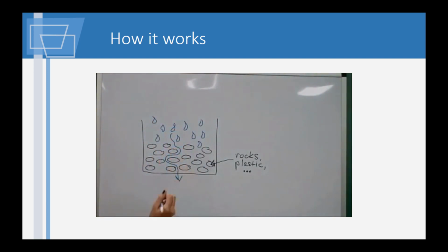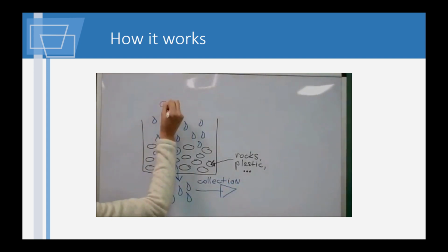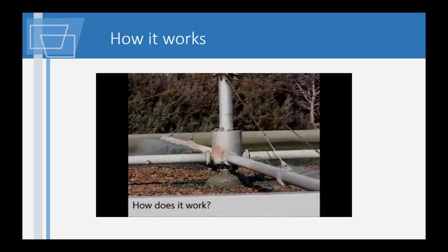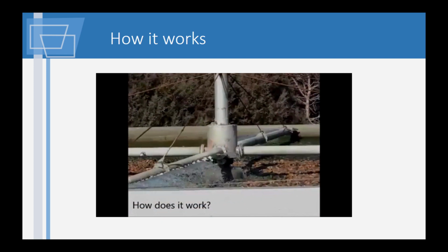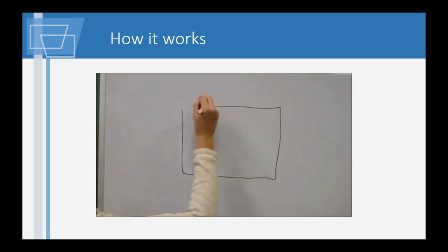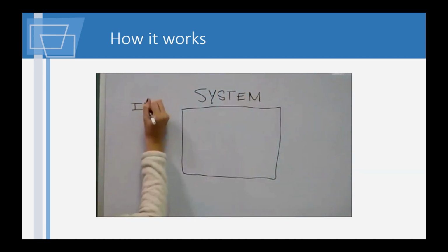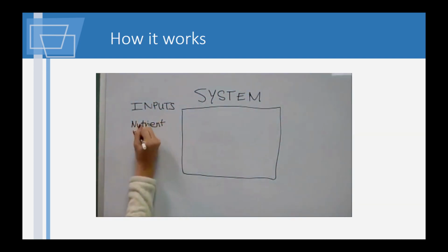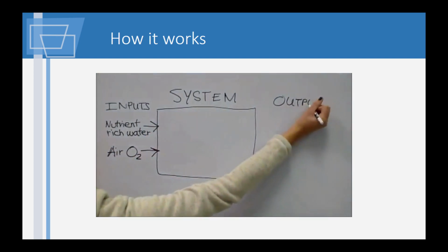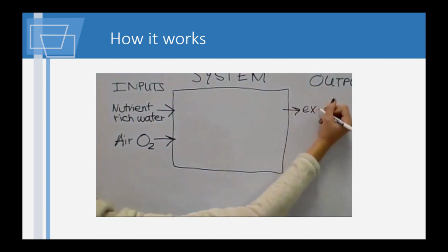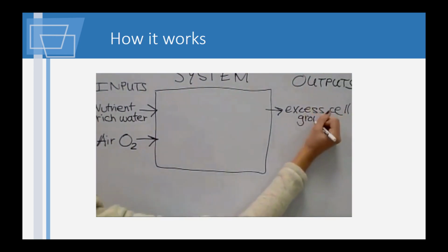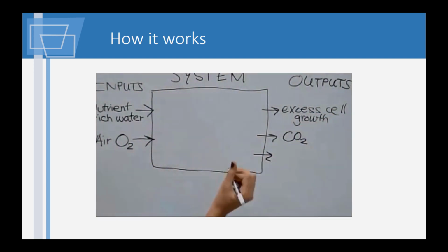The medium needs to have certain characteristics, such as low bulk density, to permit air to go through the filter, and a porous material to have good bacterial growth. To function properly, a trickling filter needs nutrient-rich wastewater and good aeration without forced ventilation. There needs to be enough shear force to remove the excess biofilm to avoid clogging of the system.